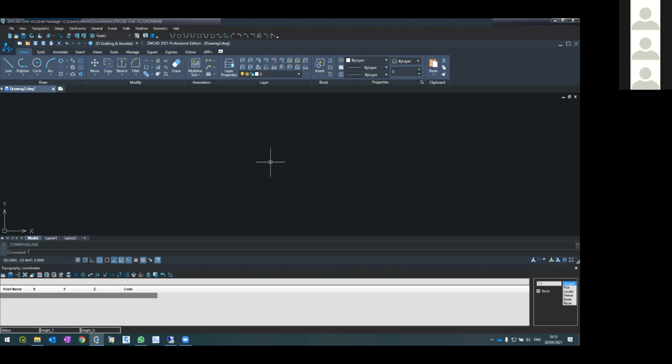We talked about break lines and what do break lines refer to, which is mainly the breaks in the surface, mainly to connect cliffs or even sidewalks in such a way that one side of the break line points will not interpolate to the other side. So meaning all the interpolation will be to the break lines and from the break lines. I hope you remember.